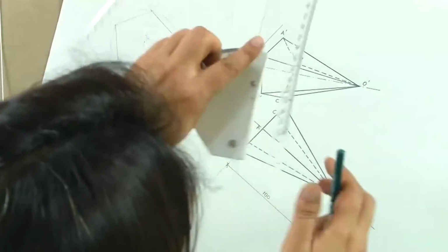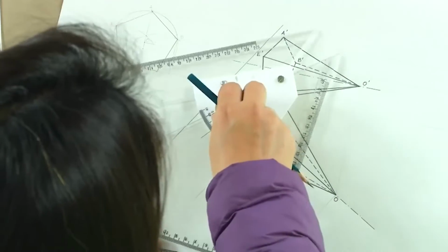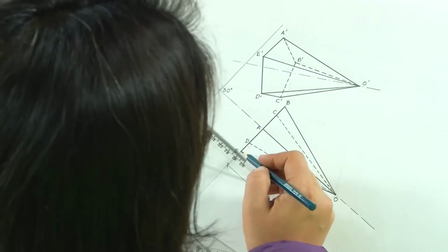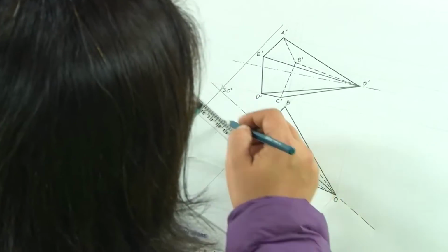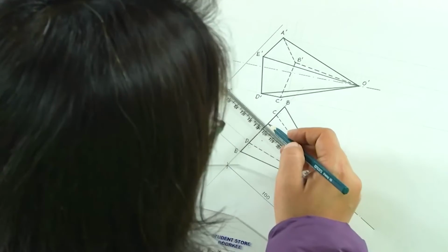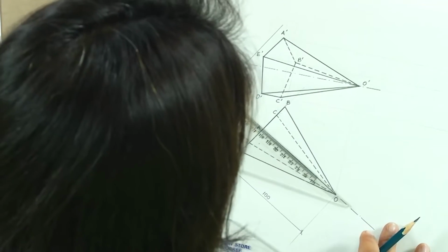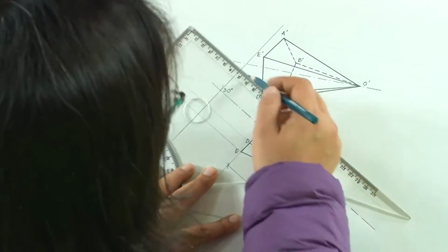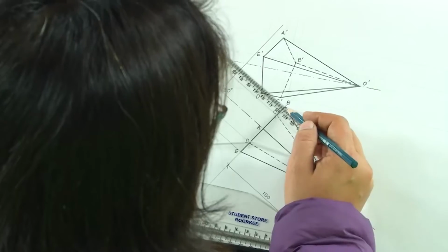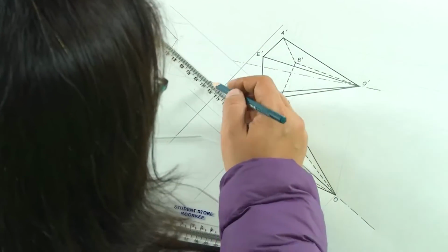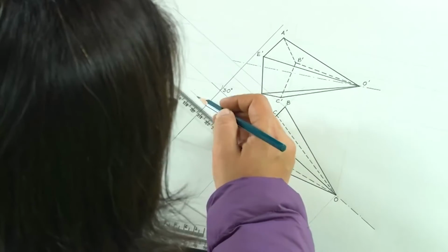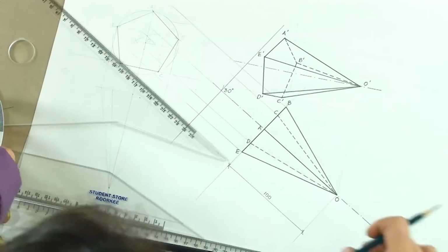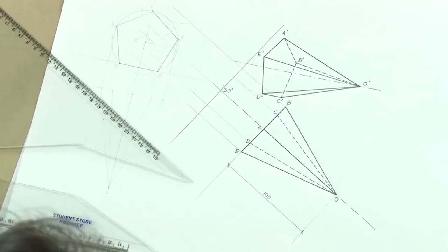All we have to do is take the projections perpendicular to this. So, this auxiliary plane we are assuming as parallel to the base. So, we get the projections of these points here. And the vertical heights are going to come from the elevation.